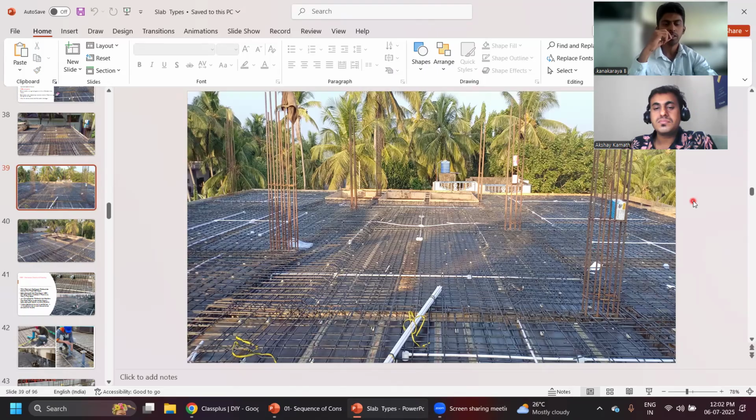Sir, they have provided the stirrups, but they have to provide them in alternate directions. If they provide one on the right side, the next one should be on the left side. It is not to get the strength, sir. It is so that tomorrow, if any failure happens, everything will not suddenly open up. The strength is already designed.